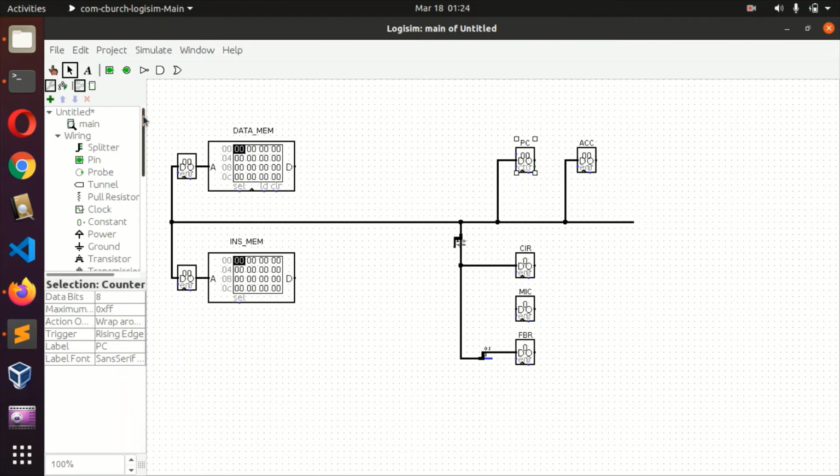Because of this high input impedance, if we have data on this data bus, on this line, it won't be affected, because these inputs have very high input impedance. It's very huge, in megaohms. So whatever we have on this bus won't affect anything, because current will not be able to flow through them. Because of the high input impedance, current cannot flow through them. As a result, connecting the inputs to the data bus is fine.